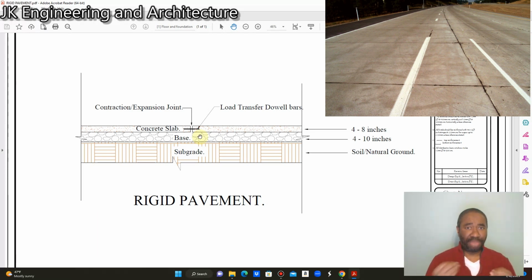Because of that expansion, the concrete surface has to have a gap to allow for it. If there are no expansion joints in the concrete, when it heats and expands in its volumetric dimension, the expansion has nowhere to go because there's no allowance for it, and henceforth your concrete is going to end up with structural cracks, and that is going to be hazardous for the traffic that is using the pavement, and it's going to cause problems for your maintenance cost.